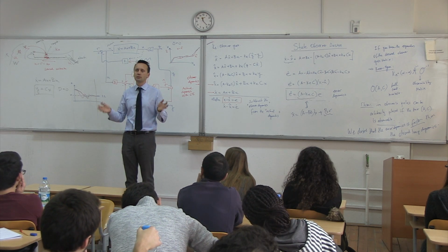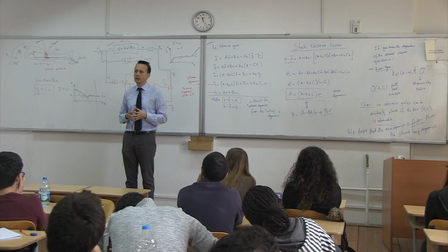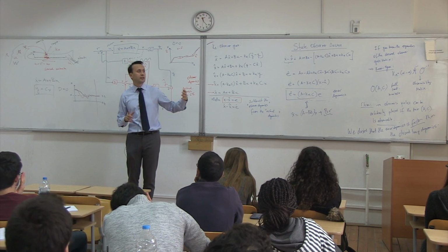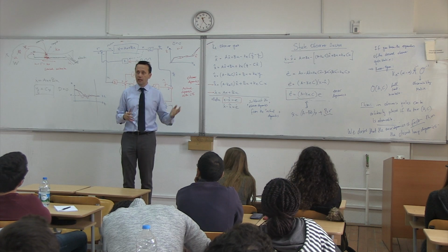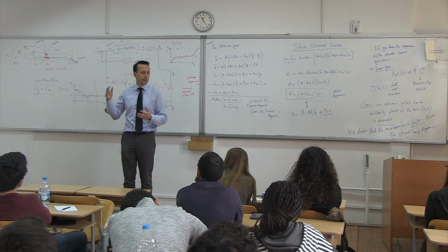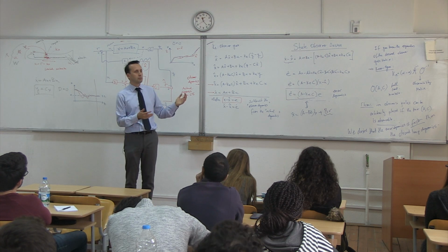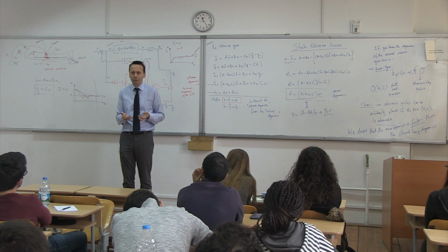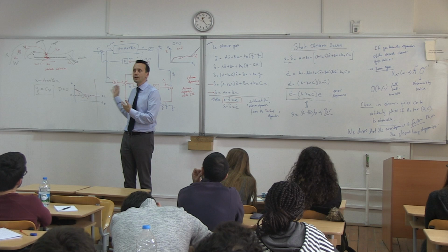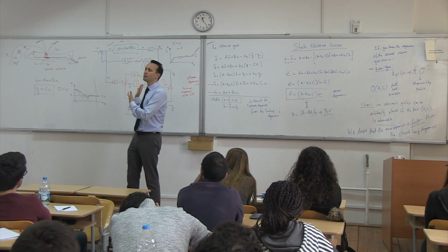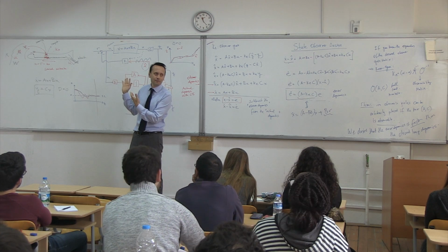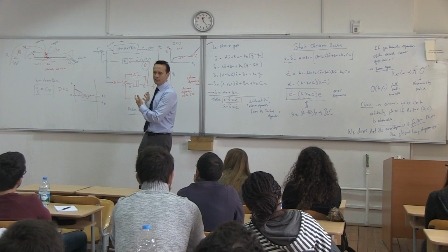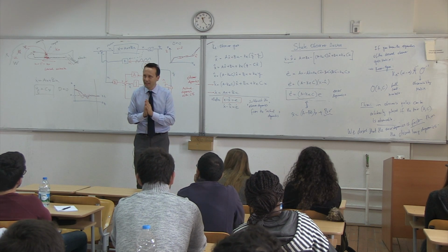Okay. You can do CFDs, you can do wind tunnel tests, you can do all sorts of things. Remember, in flight mechanics, we find the AB matrices through what? Through aerodynamic derivatives. Where did they come from? Well, you find CL alphas, you find CM alphas, betas, and all that stuff. Where do they come from? Well, you measure them in the wind tunnel, you do CFDs. And this is where all the technology really is, to find these things perfectly. If they are not perfect, the CFD people just give you some numbers, and you assume that your aircraft will perform perfectly.